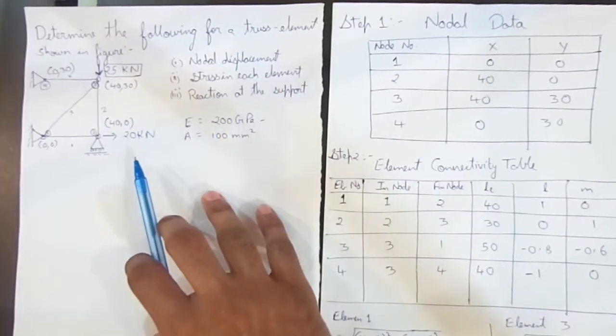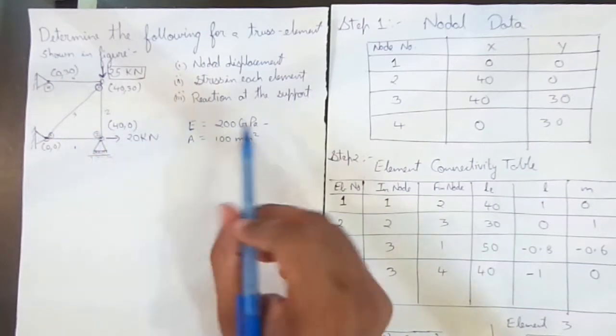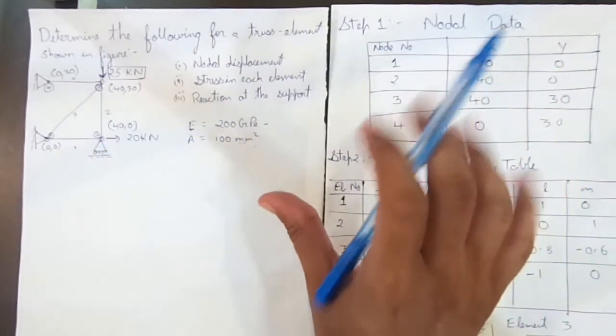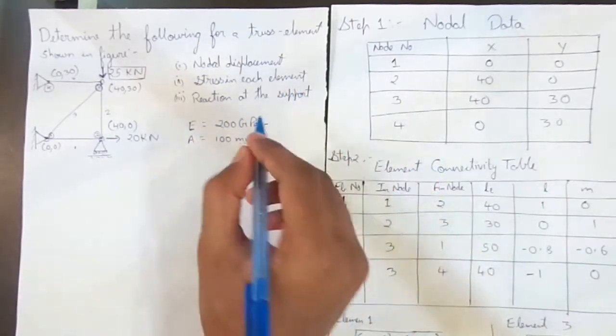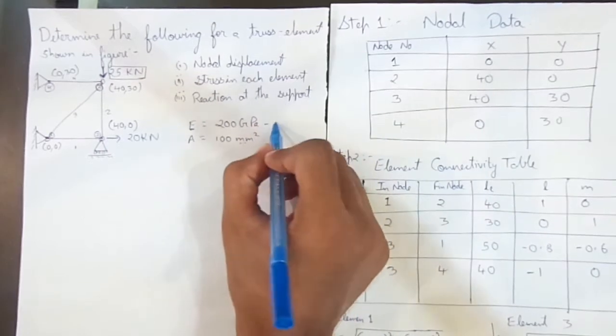So what I suggest is, if any of the other things are given in mm, you take Young's modulus in megapascal, right? I will tell you how. So 200 GPa, if I need to write in megapascal, it will be 2 into 10 power 5.